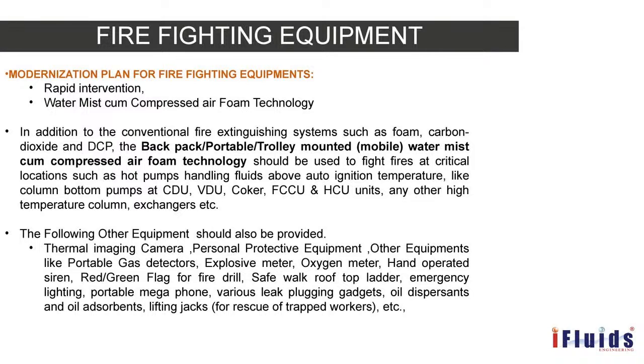Then, according to the requirement of this dry chemical extinguishing system, the design and system requirements, like whether it is a local application system or has to be provided as a total flooding system, are also outlined a little bit in this OISD 116. But it asks to refer to NFPA 17 for the limitations and precautions for the dry chemical powder equipment. So you need to refer to NFPA 17 with respect to dry chemical powder extinguishers. These things are outlined in this chapter 9.